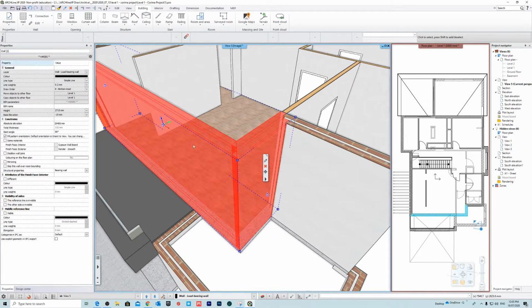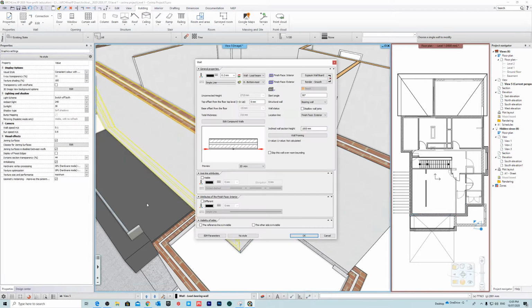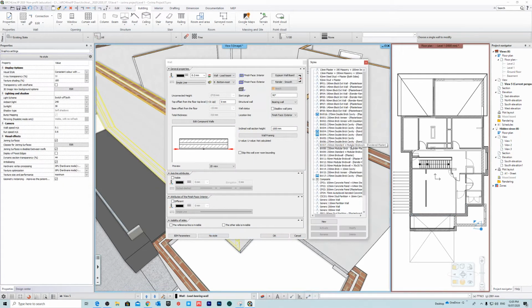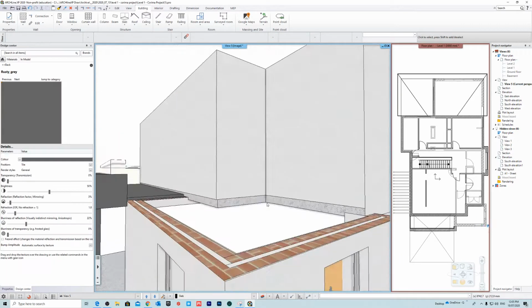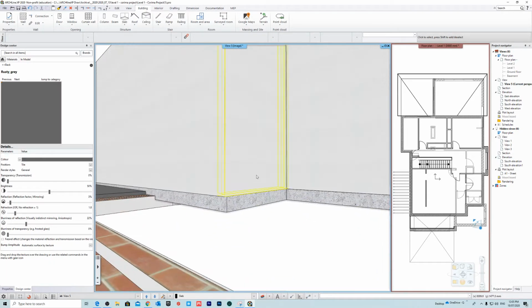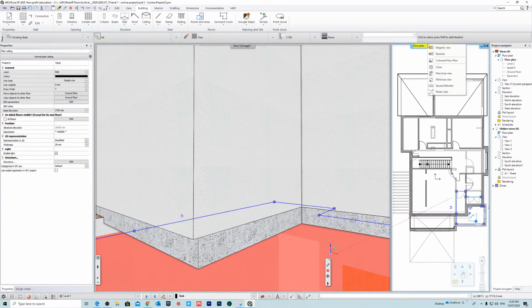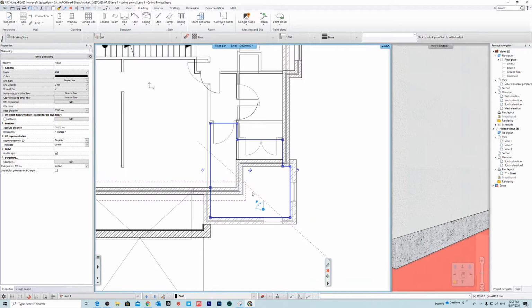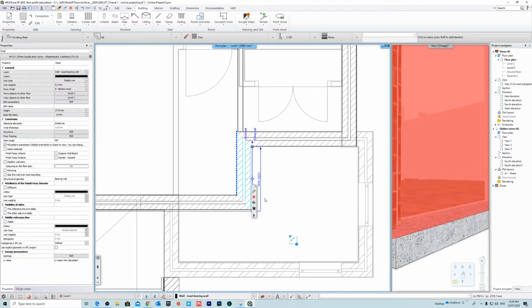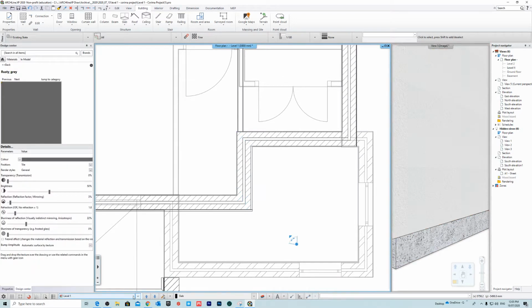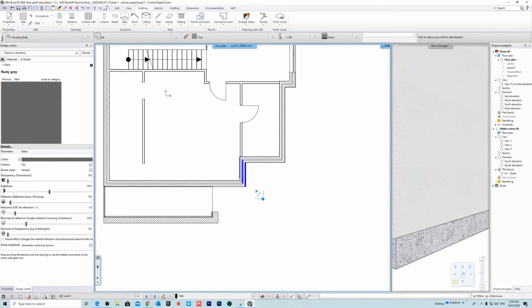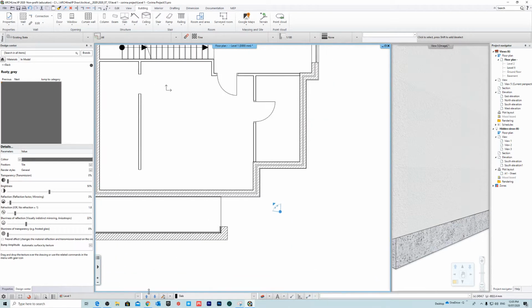Okay, and I'll just go activate, just to sort of make sure that these two walls are the same. So for this one I'll do that as well. I'll just go where it says no style, and I'll just activate BW17. Okay, and so this one we just need to move that into place as well. Okay, so we'll go back to the floor plan, and I'm just going to show the level below by ghosting it. So I'm just going to click over here and ghost this layer.